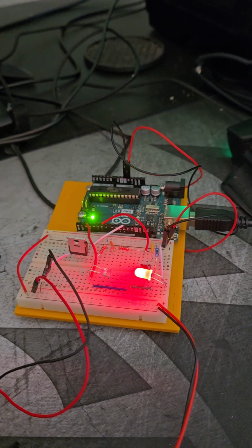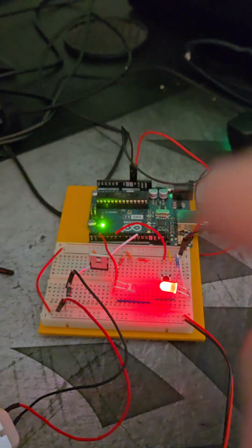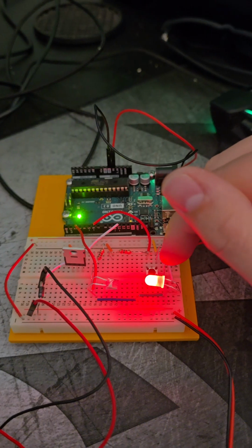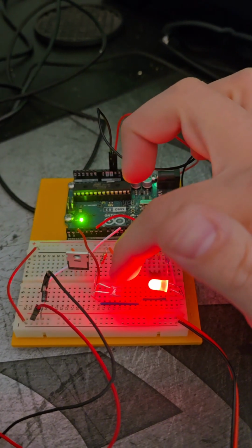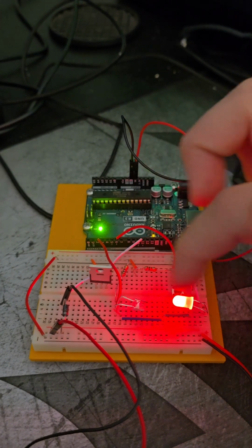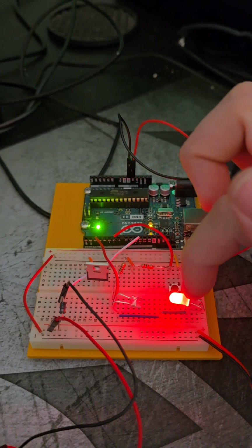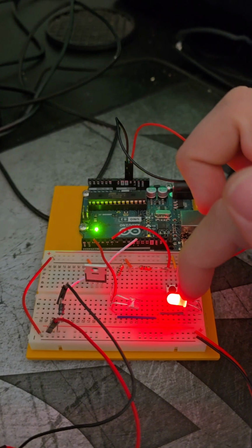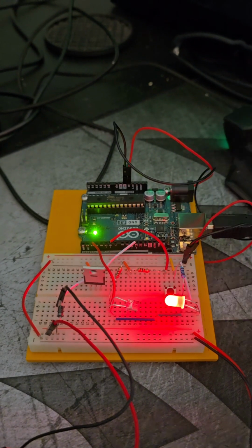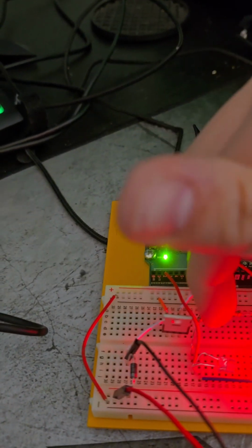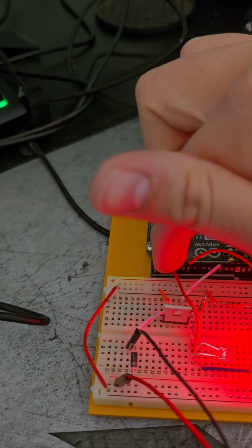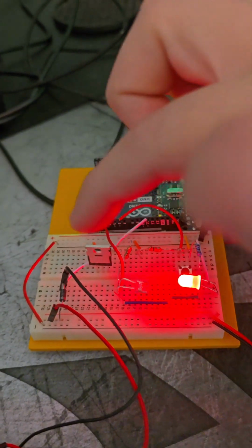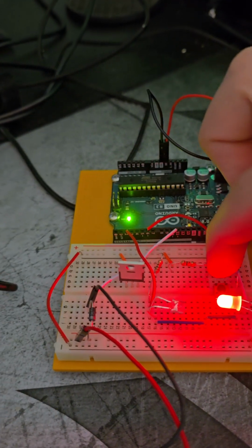And here we have my circuit. The sensors that we're going to be using are this LED and this photosensitive transistor right here. The transistor should be picking up the LED, absorbing the energy from it and giving somewhat of a current, and then sending that signal down this line right here to pin 2. And then there's some other circuits going on here for the switch to turn the propeller on and off. That just makes it a little bit easier to work with.